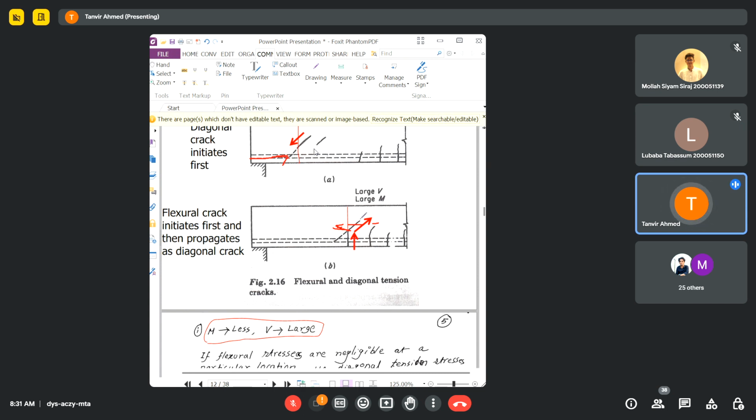But when the crack forms because of the shear force, you will already have some area loss in your concrete section. So some of the area will be lost or will become ineffective because of the cracking due to the flexure. And for that reason, the area that will be effective to resist the shear will become small, and for that reason, the shear strength of the concrete will also reduce.